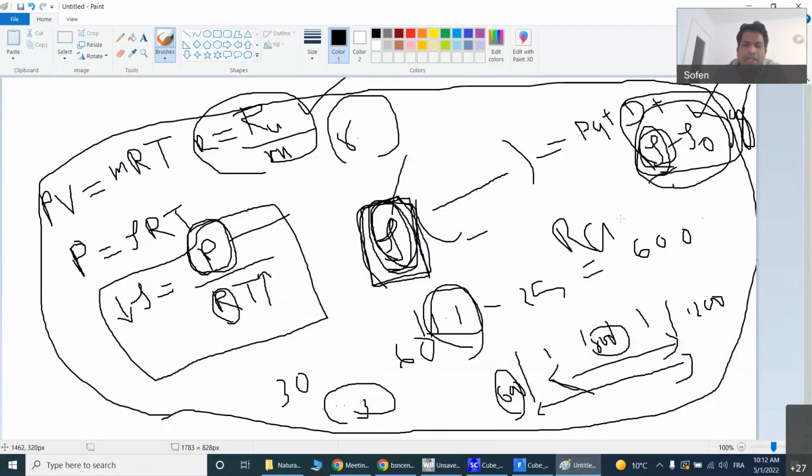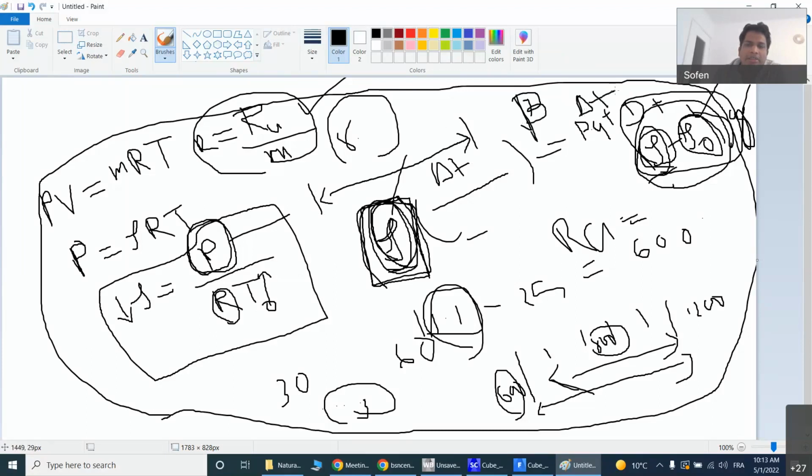For a particular Rayleigh number, you will get what your reference temperature and operating density are supposed to be, right? Your operating density is the variable here. To get that, you find the temperature. So you have to choose your reference temperature accordingly to match that Rayleigh number, and or the temperature difference delta T. In the Boussinesq approximation, we have two parameters, one is beta, one is delta T, that are used to interchange to get a particular Rayleigh number.